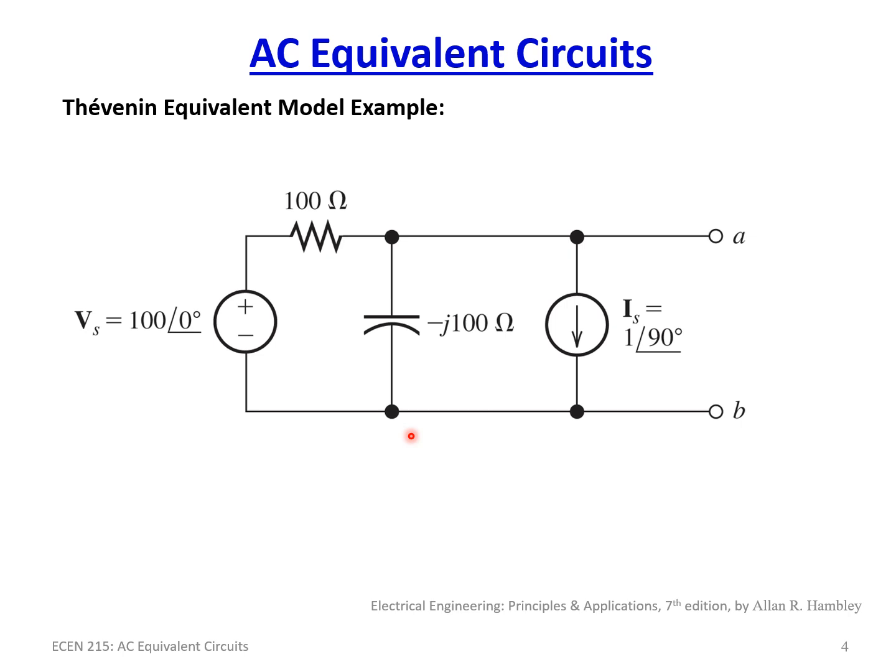So to do that, for this circuit here, we're going to do nodal analysis. We're going to start by finding a reference node, which we'll set here, and we're going to call this node 1. Since we want VAB, the open circuit voltage, all I need to do, since this is my reference node, is solve for V1, and I'll have my open circuit voltage.